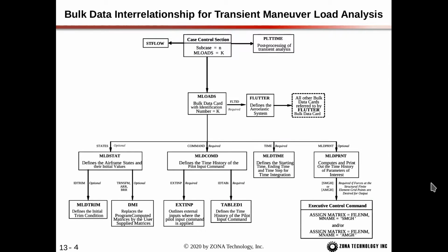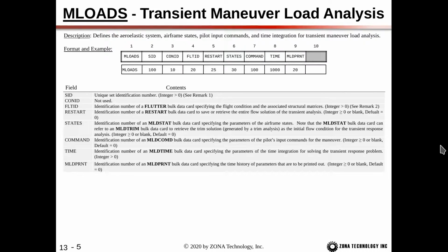And this is the bulk data relationship for the maneuver loads analysis. So we have the case control section, which refers to the MLODS card. The MLODS refers to the FLUTTER card to define the aeroelastic system. It doesn't perform a flutter analysis. We just use this to pick up the analysis parameters. And then the MLODS refers to the MLDSTAT, the MLDCOMMAND, the MLDTIME, and the MLDPRINT card. So we'll go over these cards.